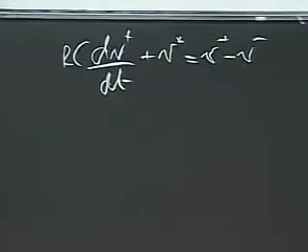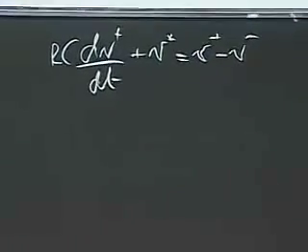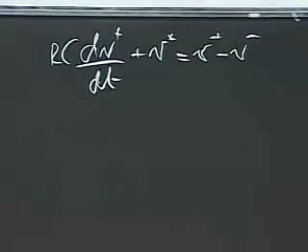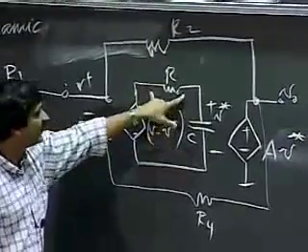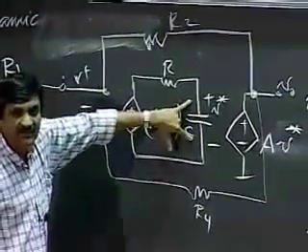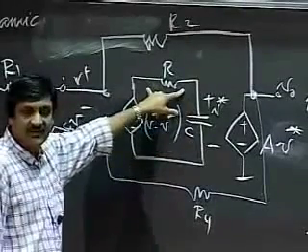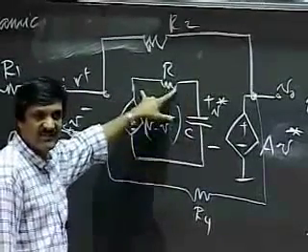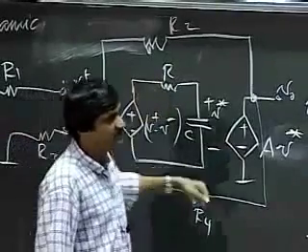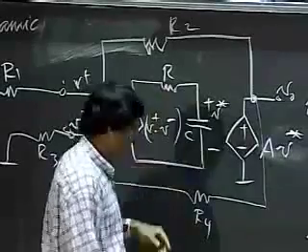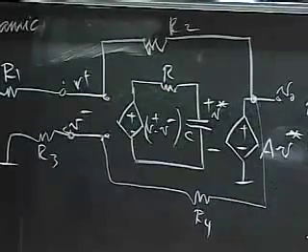You've done this millions of times before, but yet again, this voltage here is equal to the drop across these two. And the drop across these two is V star, the drop across C, plus the current through the capacitor, C dV/dt, times the resistance R. Or you can apply the node method as well and get the same expression.